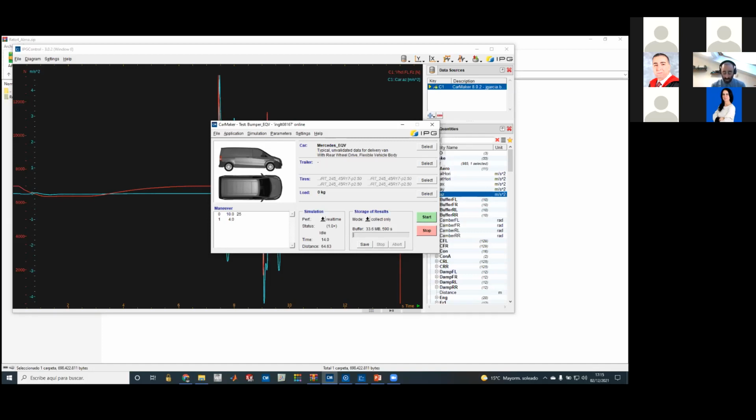Regarding the second question, regarding the vibration dose value, you asked if there is any threshold for the vibration dose value. What we need to understand is that the longer the signal, the lower the comfort. So the vibration dose value is a way of trying to make comparable a short signal with a really long signal.